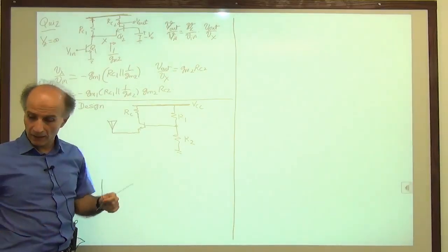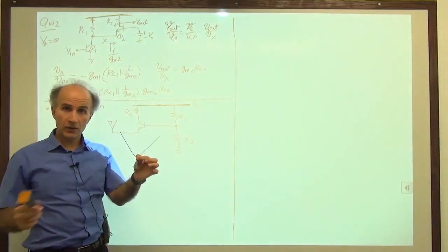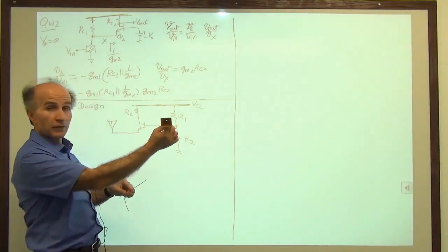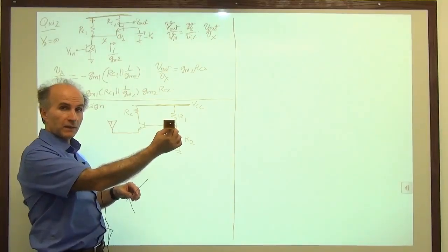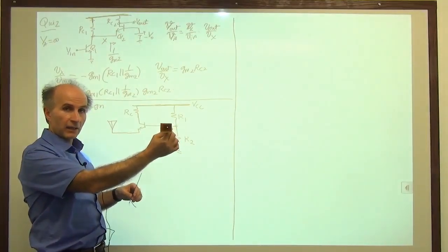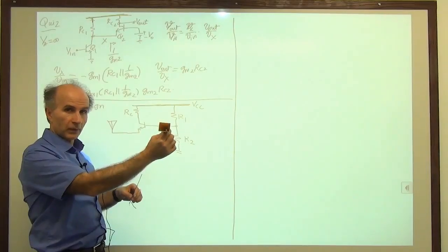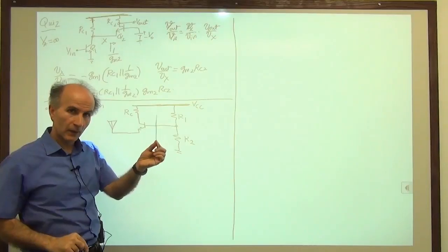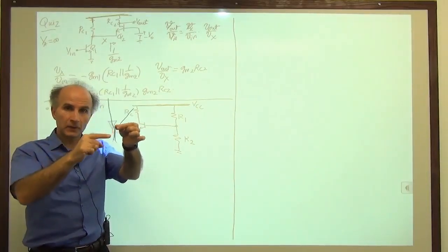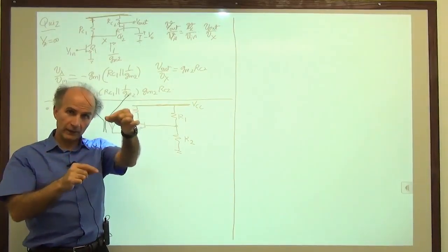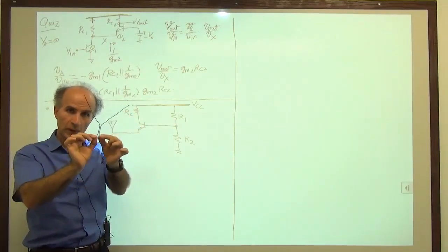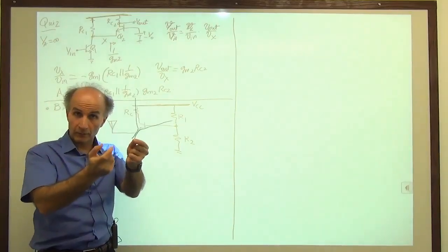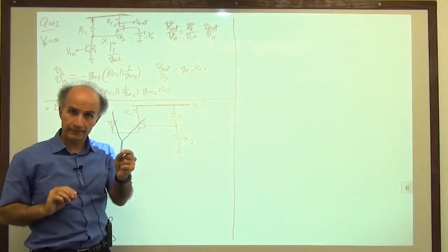By the way, this V can be created in 3 dimensions, in which case we get a horn antenna. This is called a horn antenna. If you look very carefully, you can actually see there's a hole in the middle, which means it doesn't have any connection between the two terminals. But anyway, let's just focus on this. We see that these two wires are not connected. That's how an antenna is created. We have one wire here, one wire here. If we apply a signal to this, let's say a 2.4 gigahertz signal for Bluetooth, then it radiates.